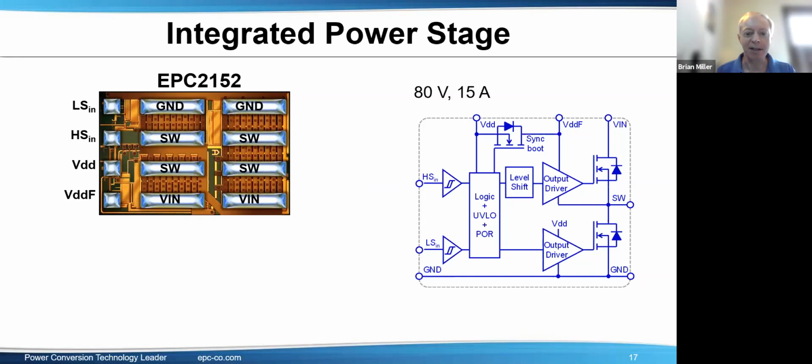I don't have the details, but for example, if there's an under voltage lockout signal that goes through here, that wouldn't be good. It would turn off everything, because if you're not using the upper FET, the chip doesn't know if you're about to turn it on, or if it's permanently tied to ground. So yes, you do need a boost capacitor.